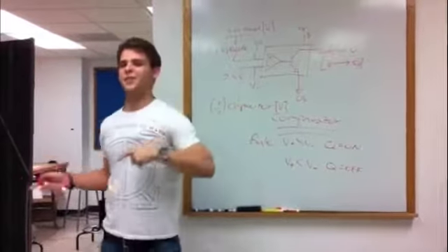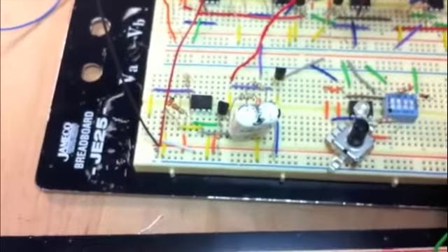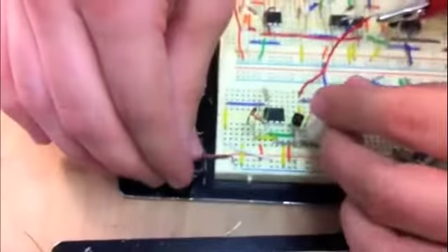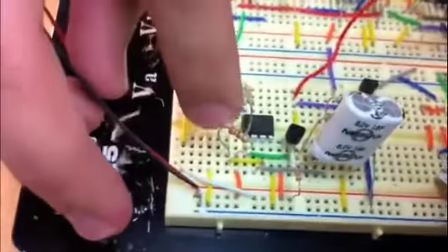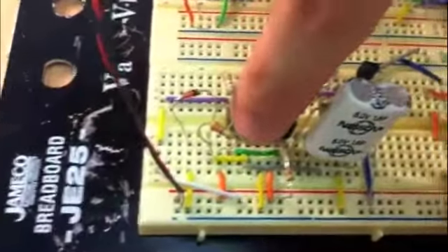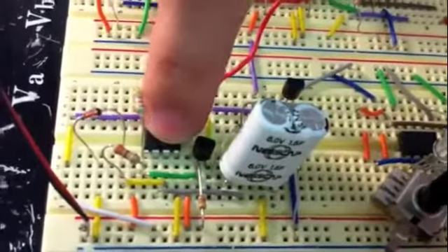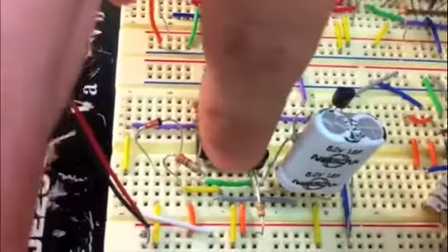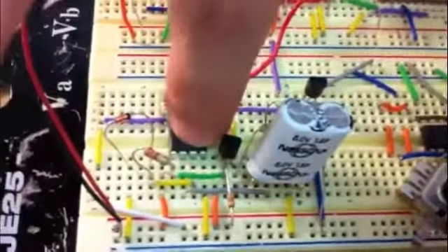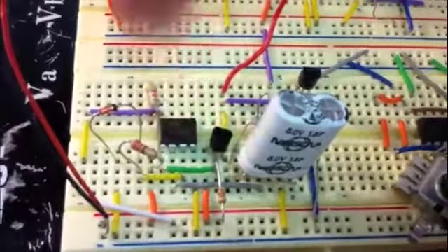And then we go over to our circuit. You can see here that we're expressing a light going into the solar panel, which is going through these wires into this rail here. What this rail does is, here's the diode, so we have the solar panel voltage going through the diode and out through this yellow cord into the third pin of the comparator. So it goes in through the diode, and it constantly reads 2.5 volts in that third pin. That third pin is V minus.